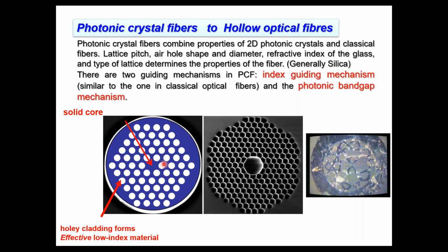And one important property of such fibers is that they can be endlessly single mode. They can act as a single mode fiber for a wide range of wavelengths, which is not applicable to the common optical fibers used today for communication. We know whether a fiber is single mode or multi-mode will entirely depend on the wavelength of operation, its geometry, and the values of the refractive indices N1 and N2.